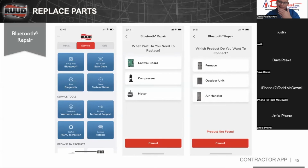You said pressure switch. Where would you put a pressure switch? Well, I know Floyd had touched a little bit about it, like if you have, say, a leak in the coil with the flammable refrigerant that's coming in the future. That's all going to be incorporated into the equipment. You're not going to use these auxiliary switches for that stuff. Gotcha. Okay. These auxiliaries are for your typical wet switches, or like propane pressure switches, things like that. You can label them whatever you want to add. The safeties are already incorporated on the equipment. Gotcha. Okay.